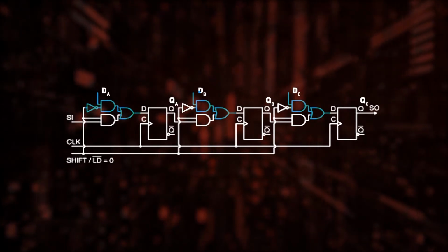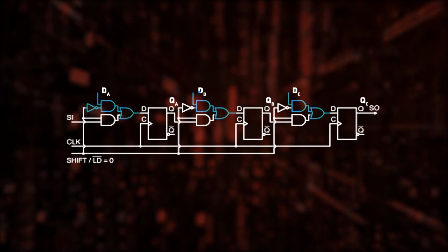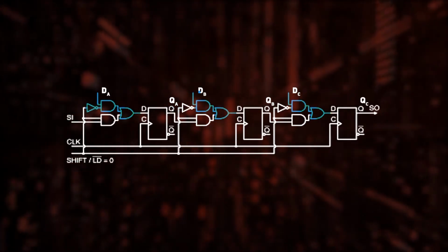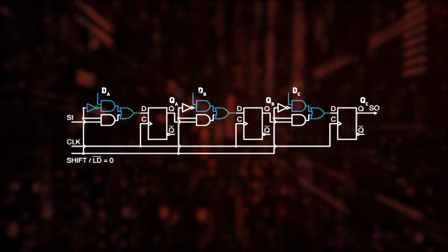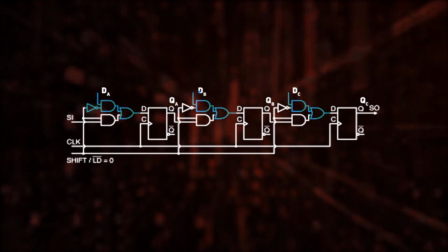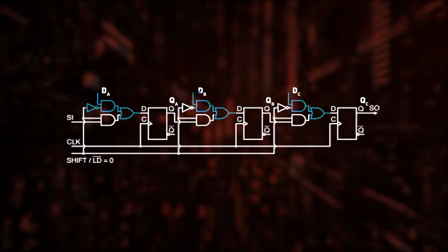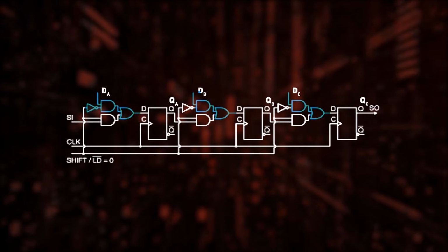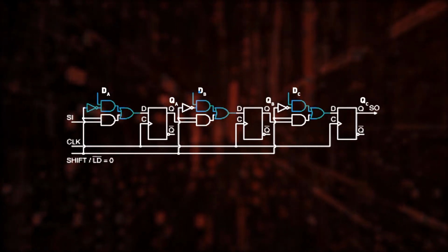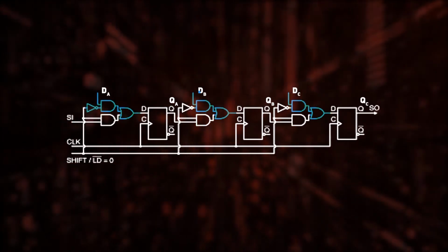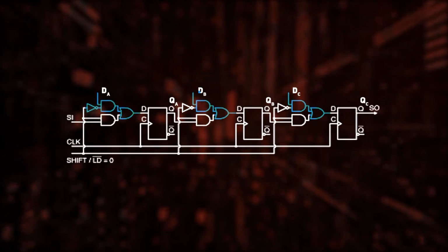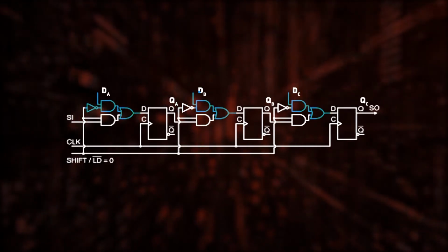After loading the data into the register, the values have to be shifted. To shift it serially, a flip-flop needs to receive its input from the previous flip-flop. In that case, for a PISO register, each flip-flop requires 2 inputs, one from outside to load the data and the other from the previous flip-flop to shift the data. We cannot accept both the inputs separately because the D flip-flop only takes one input at a time.